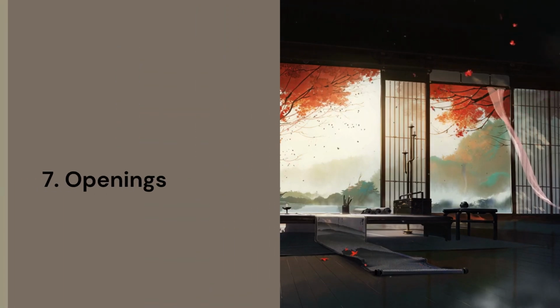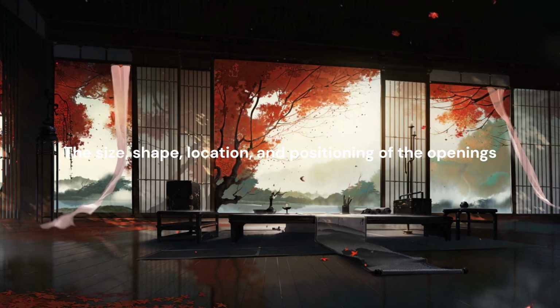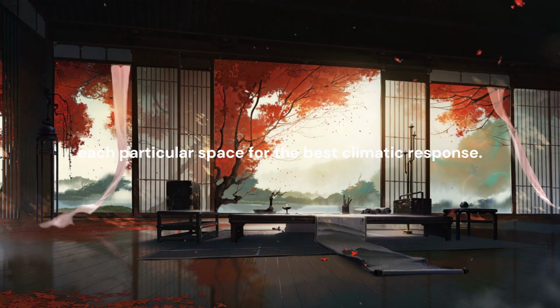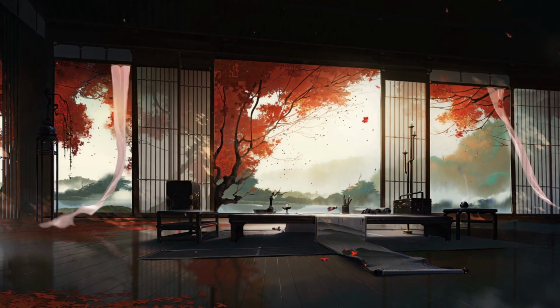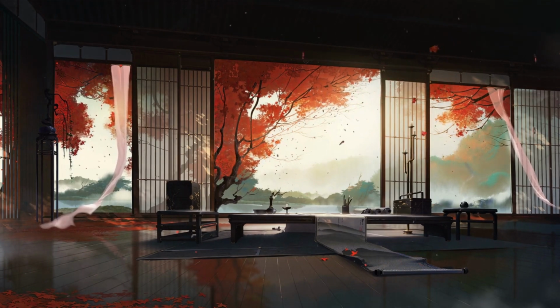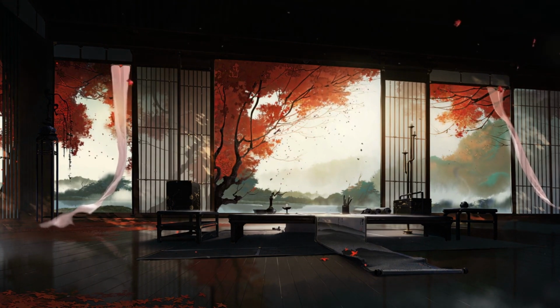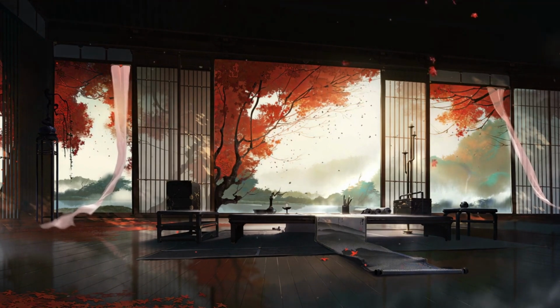7. Openings. The size, shape, location, and positioning of the openings can be curated to fit the needs of each particular space for the best climatic response. Key design strategies. 1. Place windows higher to act as ventilation points. 2. Place all the openings on external walls to allow cross-ventilation. 3. Prefer small openings to avoid heat stagnation inside the building.